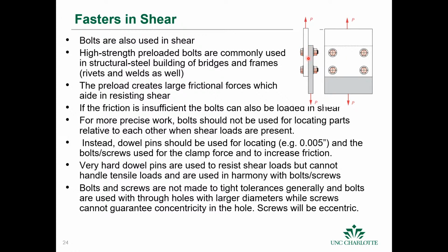If you don't have enough friction though, then the material doesn't pick up that shear stress, the bolts pick up the shear stress, and you put the bolts in direct shear. Okay, so it's another reason why you want to have sufficient preload: to get the material to take up not only the axial load but also the shear load, so that shear is not experienced by the bolts.